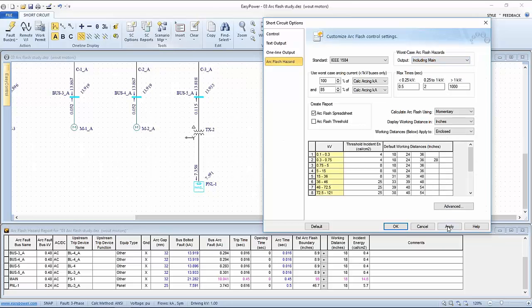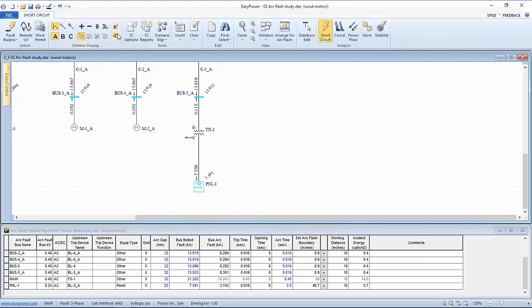By including the protective device and showing the energy, I put myself in a safer condition than I am with that protective device inside the panel. So that ends up being the answer. Playing with the calculation time doesn't solve what appears to be the real issue here, and that is a poor location for the protective device.